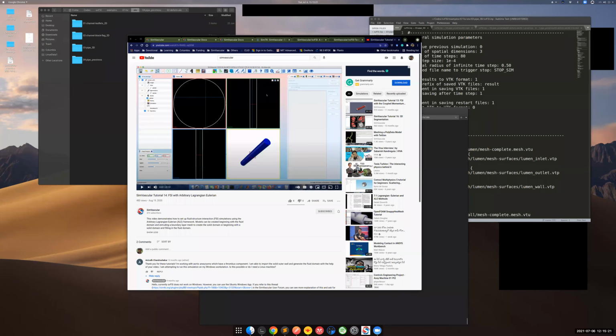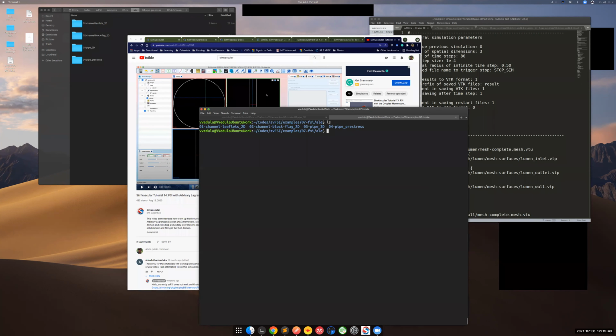I will also encourage people to go through a little bit about the mesh generation for FSI. One of the challenges with FSI is you want to have a mesh that's conforming. So svFSI, the code that we use, uses a monolithic coupling, which means that, if I can explain that, maybe taking an example here.